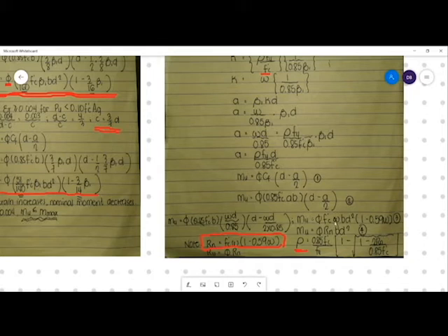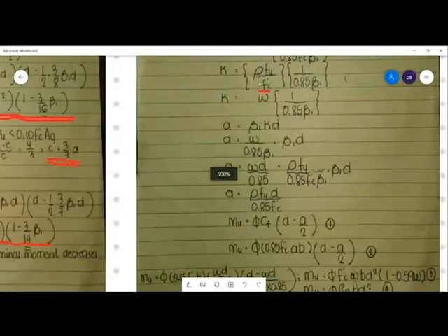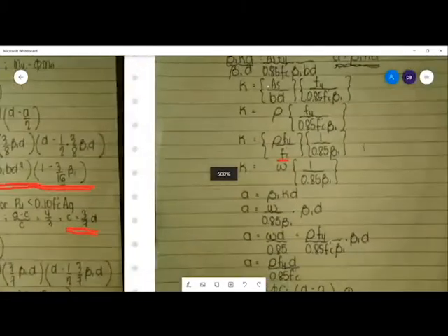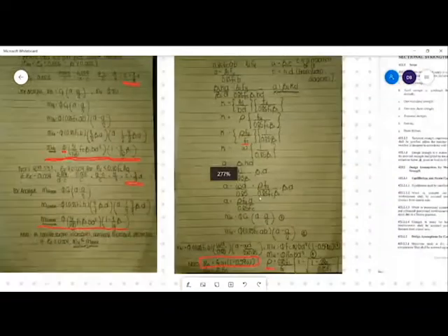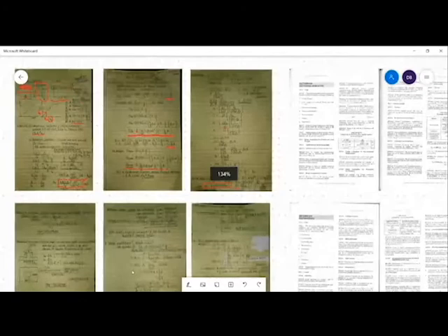If we decided to use formula 3, we are able to know that omega is equal to rho Fy over F prime c. Our rho is equal to As over bd. So, let's go back to the problem that we're solving.